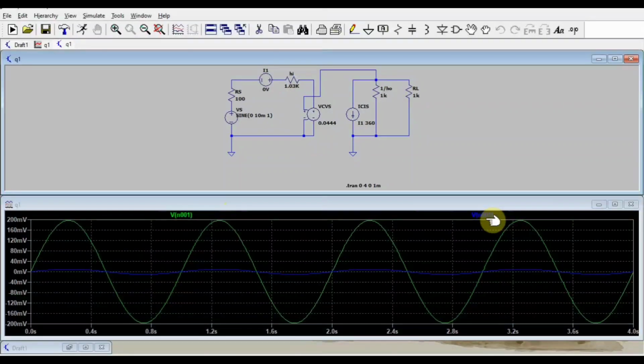These are really the nodes, the nodal voltages. We know what nodal analysis is: nodes are points where we have common voltages. So these are nodal points. The analysis becomes much easier if we are able to name them, and LTspice enables us to name different nodes. So let's look into that.